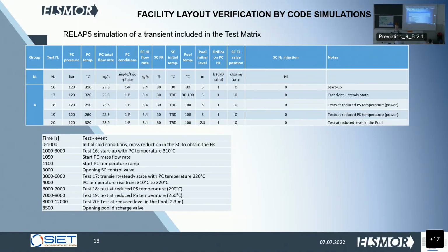We may also have other parameters that can be set in the plant. For example, we have a measurement orifice for flow rate at the outlet of the vertical tube heat exchanger that introduces some pressure drops. This can be changed. We also have another flow orifice to set pressure drops.